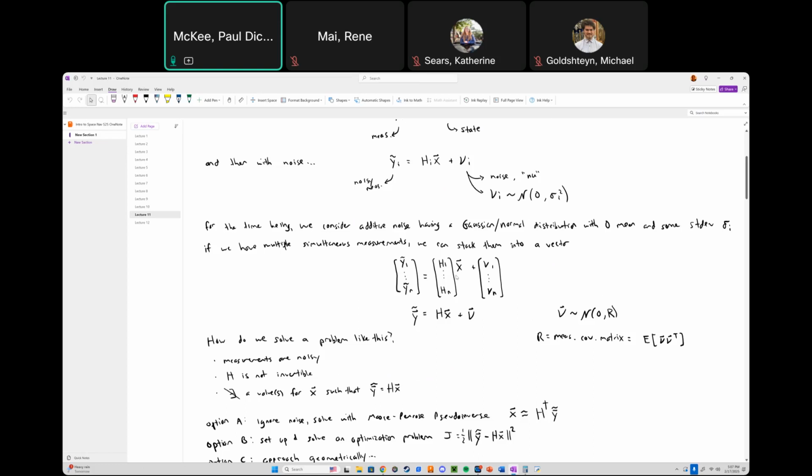If you're measuring some radio signal from the Earth to determine something about your position, and then a minute later you take a different radio signal from a different ground station on the Earth, that's 2 different measurements, but in the one case you're measuring your state at some time t, and in the other case you're measuring your state at t plus 1 minute. Those aren't the same x, so you can't just stack them like this. That's not how that works.